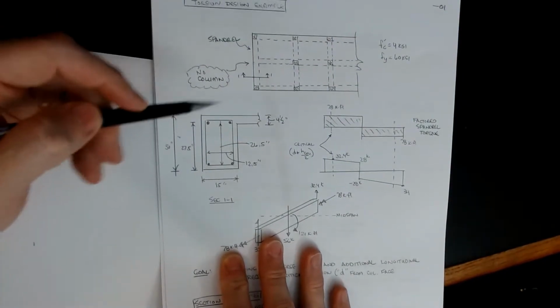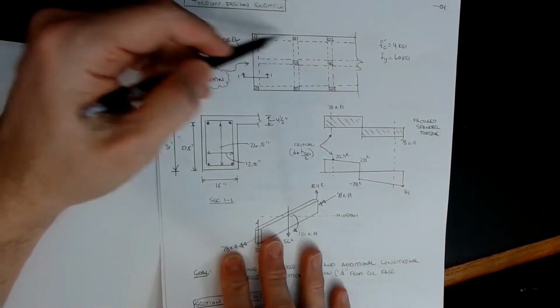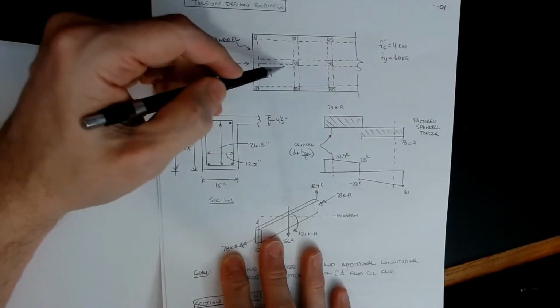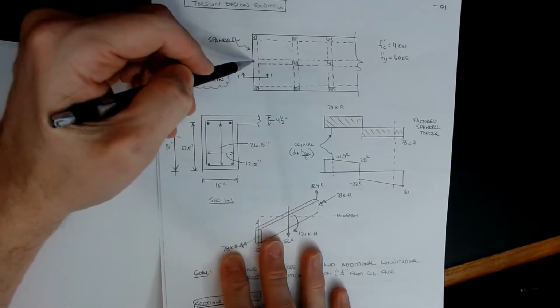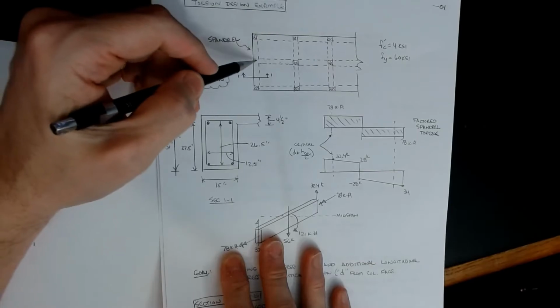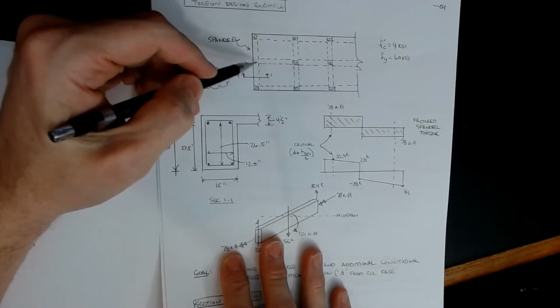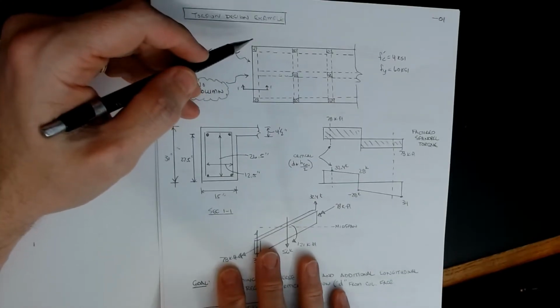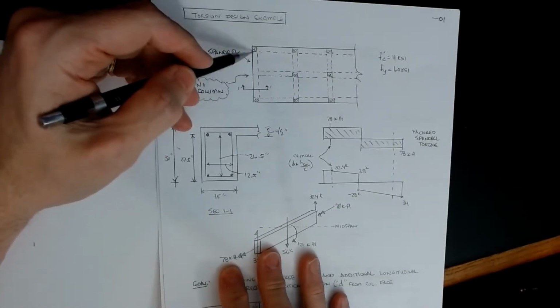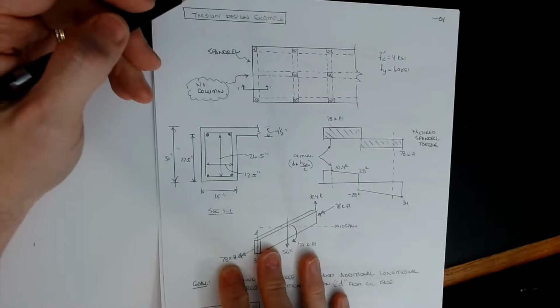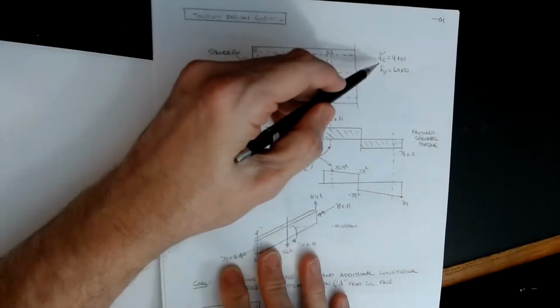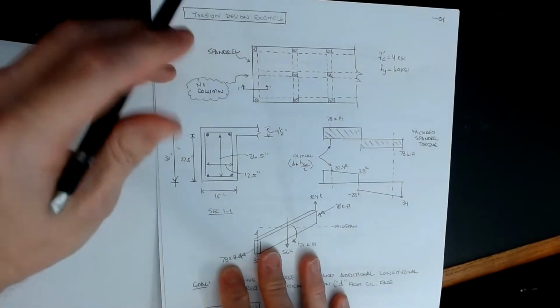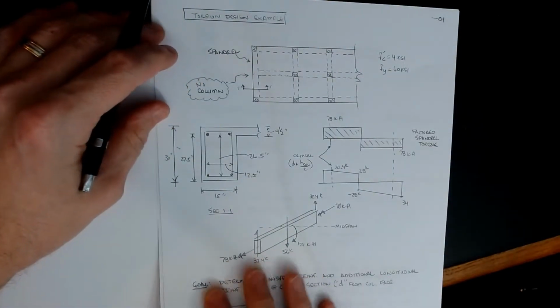What's happening is that there are beams that go between the girders, and then this beam ties into this girder but does not have a column, so this is going to put a shear load and a torque into this edge beam. This edge beam is known as a spandrel beam, because it's around the edge of the building and spanning between columns, so you may hear that term. We're going to use f'c of 4,000 psi and fy of 60 ksi.